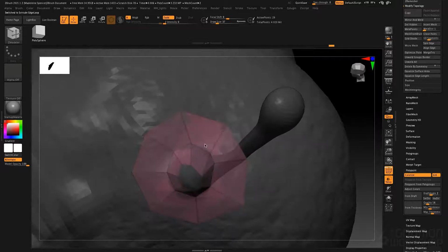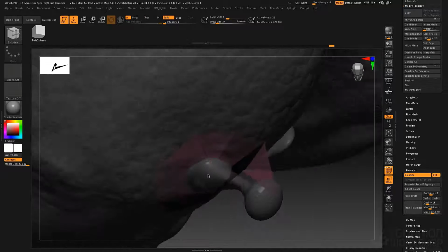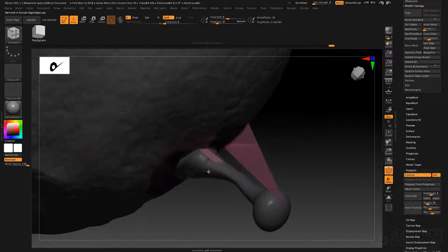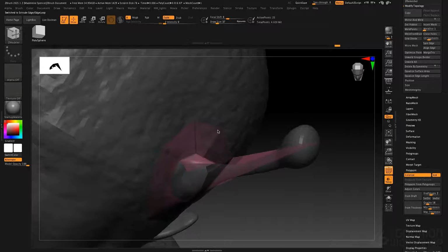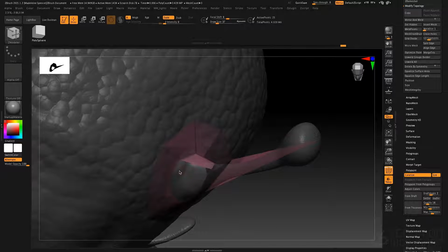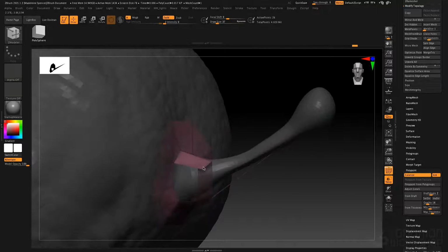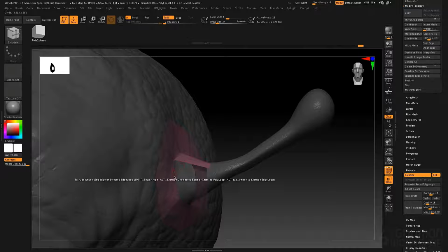Now that's not quite what I want, because you see it's actually projecting through there. So what I will do is I will just grab this face, tap the Alt key, so I'm just extruding that up. And then I'll grab this one, extrude this up, and you see it's naturally snapping to that point. And I can grab this point and bring it up. Bring this over here, drag this up, and it's just naturally snapping. Make sure that I grab this point here and then move that. And then we'll grab this and bring this up.